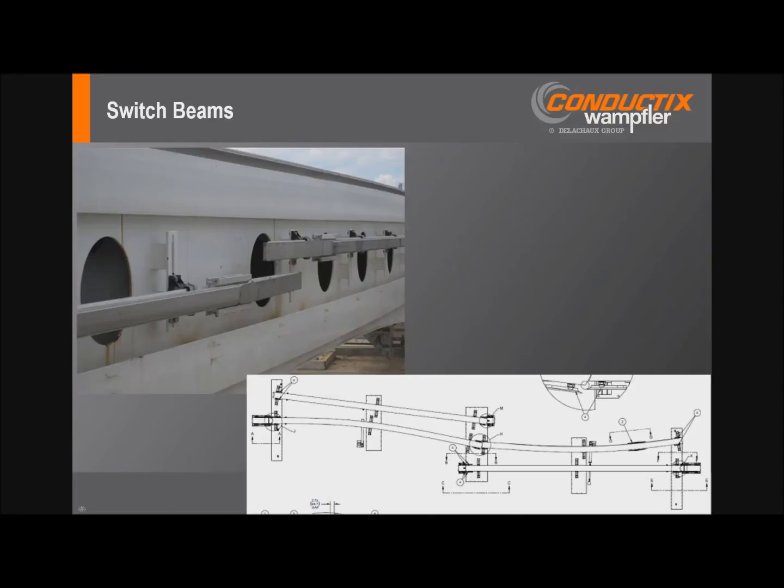Guideway switches, another kind of complicated area. They really come in three general configurations: sliding beam, rotating beam, and articulating beam. Each type imposes some requirements and limitations on the power rail system, which would include collector shoe length, vehicle speed, switch point geometries, and conductor orientation, which must be taken into consideration to ensure a good system. So it's critical that the minimum electrical clearances are maintained through the full range of switch movement, because it's not uncommon to have live conductors passing by grounded elements or opposing polarity conductors.